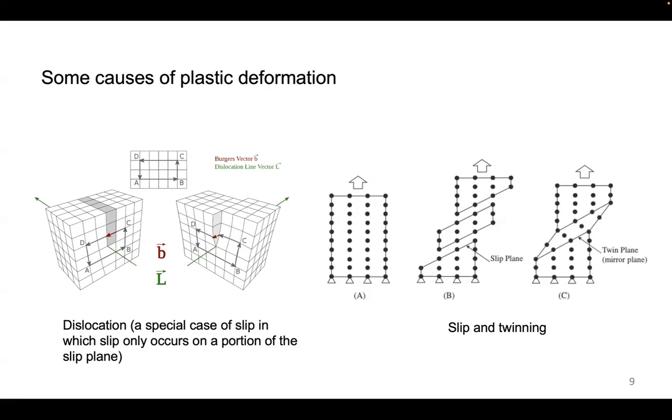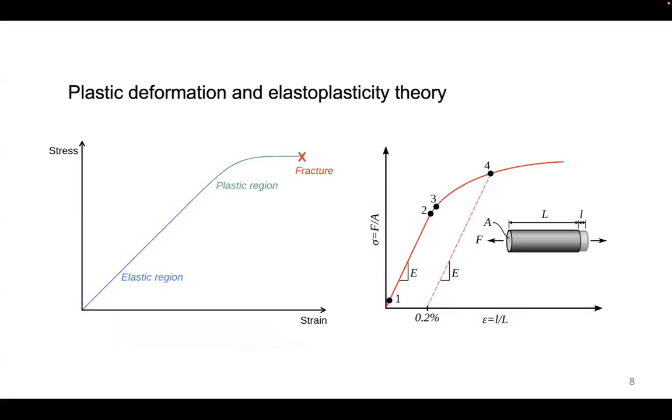One important characteristic between damage and plasticity is that when you load a material, you can see both degradation from the plastic deformations and from diffusive damage, but the difference is on the unloading. If you unload a damage model, the slope would degrade, versus if you have plastic loading, you're assuming that the elastic unloading paths are parallel to each other.